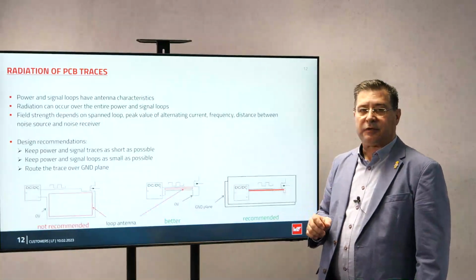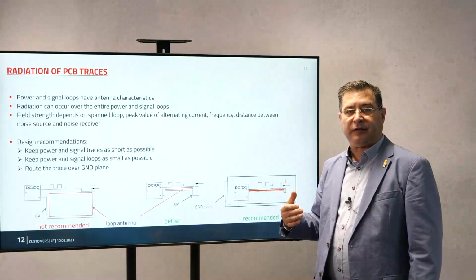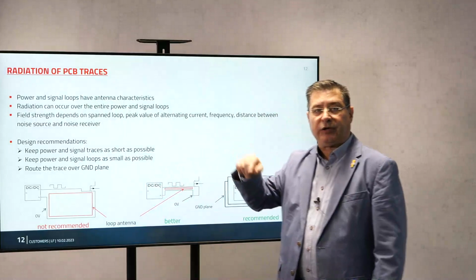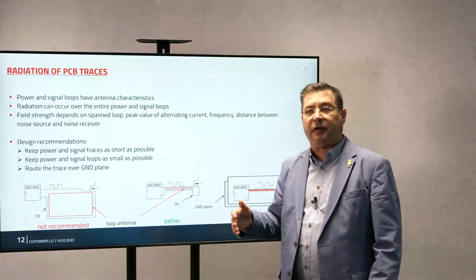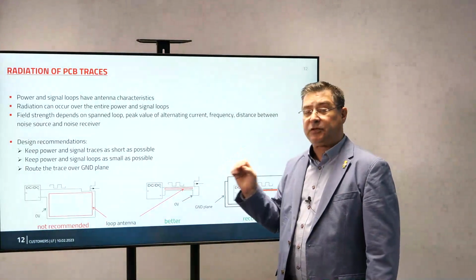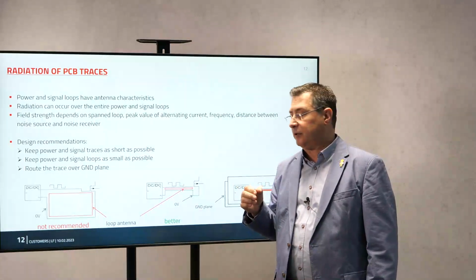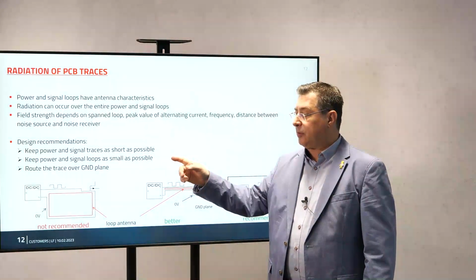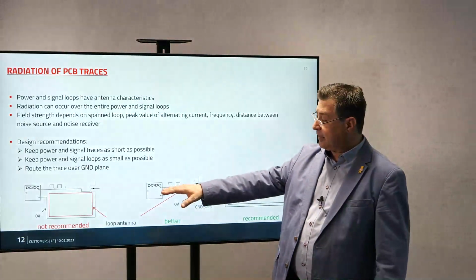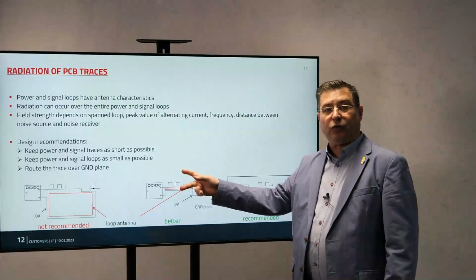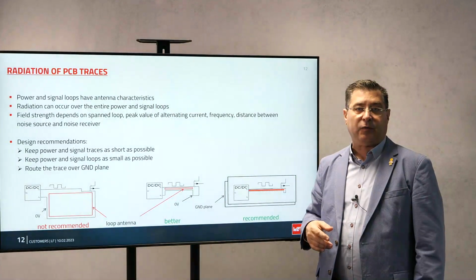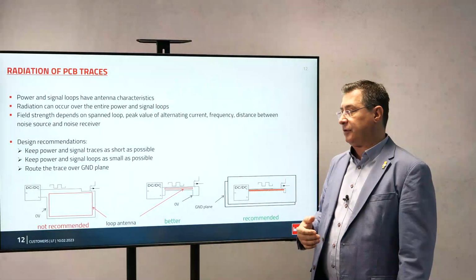Now, also for the controller and the MOSFET, you have to consider it like a digital connection, because actually the controller is transmitting a digital signal. It's maybe not a very fast USB signal, but it's a digital signal because it's rectangular. And because it's a rectangular signal, you have to consider it like a digital signal, and you have to take care about the return path, about the impedance of the tracks. So try to keep the tracks identical in length, try to keep them close to each other, and then you may have fewer problems with this fast rise time, which can occur from the controller to the MOSFET.